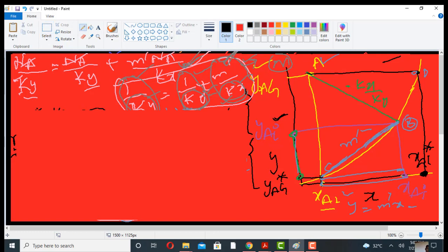The overall resistance is 1 over Ky and the individual. The fraction of resistance provided by the gas phase will be equal to 1 divided by small ky divided by 1 divided by capital Ky. This is the fraction of resistance provided by the gas phase.